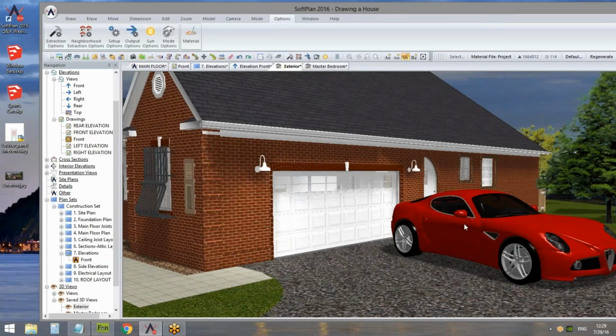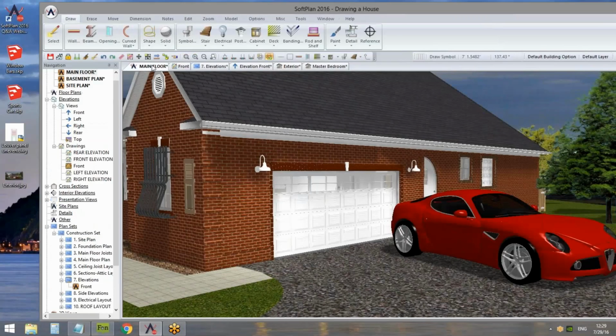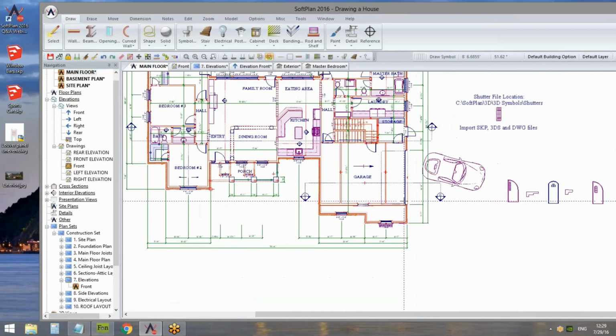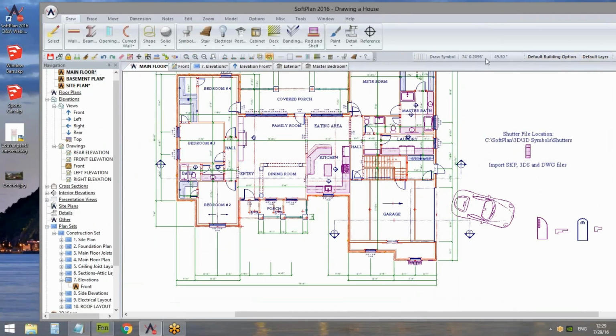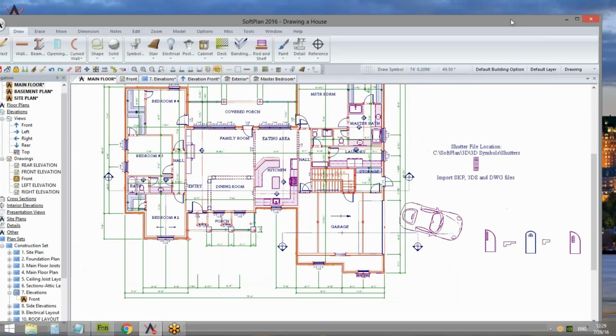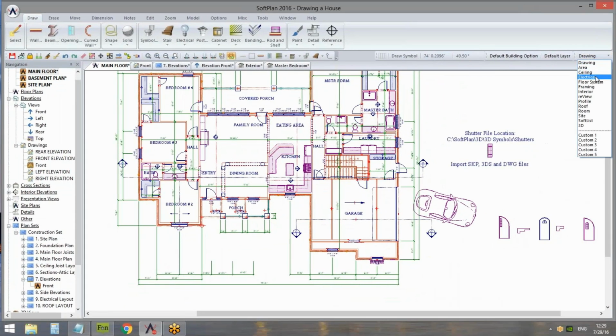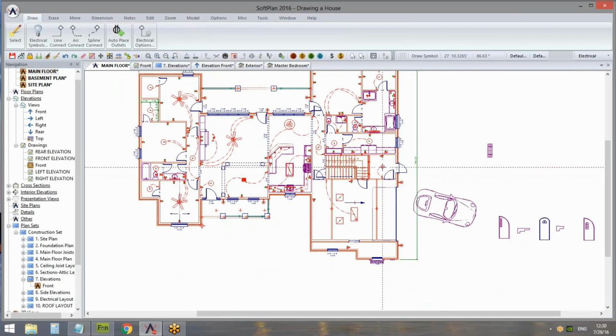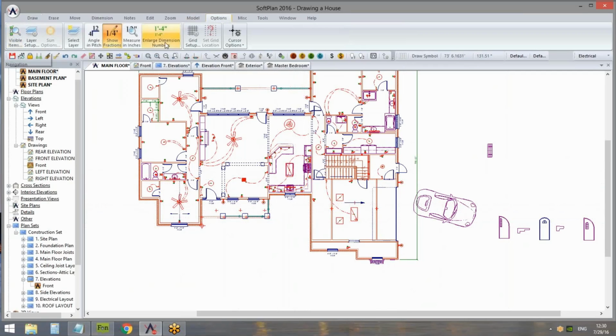Now there are some other questions that we had submitted to us that I can kind of show you and walk you through. So for instance, if you were on your floor plan and you went to electrical mode and you don't know where your notes went, so all you're seeing is arrows or shapes or anything like that, what it could be is notes could be on their own layer, which you'll need to turn on for this mode, or it may just be a matter of turning on notes in your visible items.